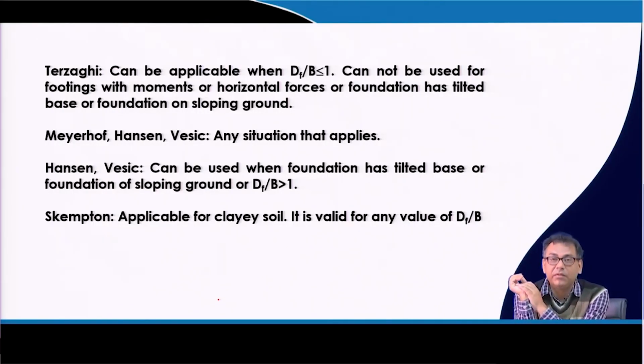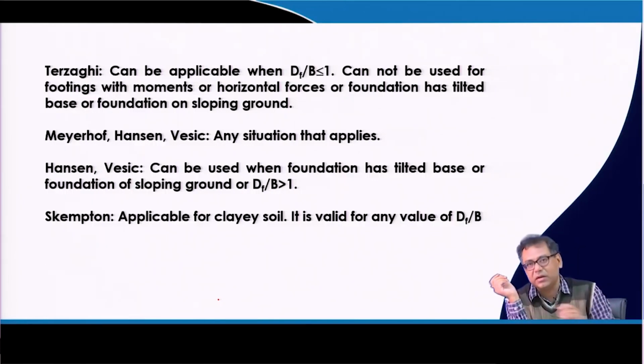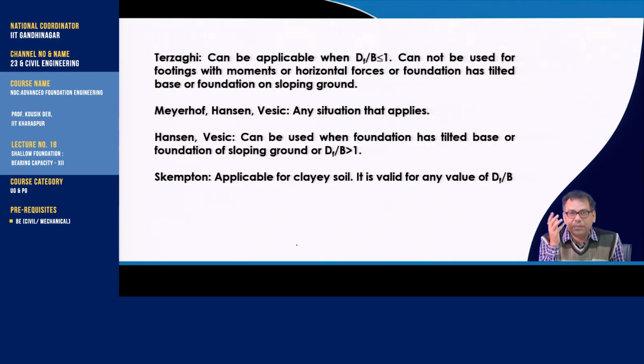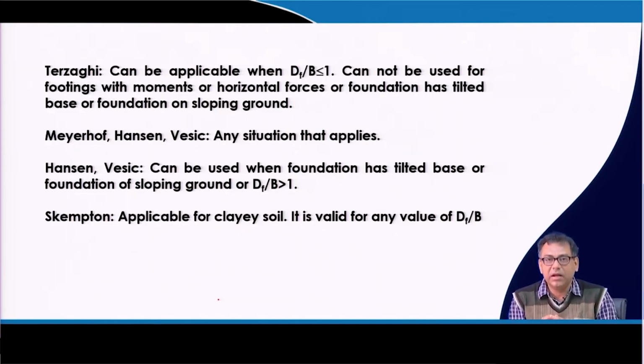And then if your foundation base is within the width, you can go for the Terzaghi for simple conditions, but if there is a different loading condition or a moment or other conditions, you cannot use the Terzaghi. So, depending upon your requirement, you have to select which one you will use, and as I mentioned, Meyerhof, Hansen and Vesic, all these equations can be applicable. And now the question is when I will use these equations. That also depends on the availability of your loading and the other conditions.